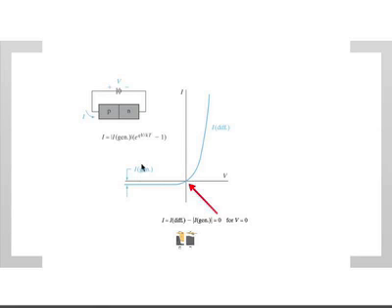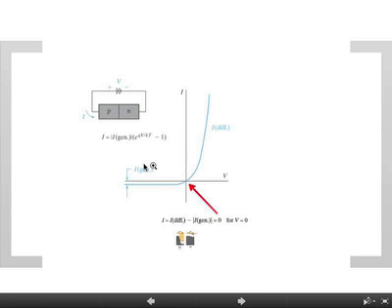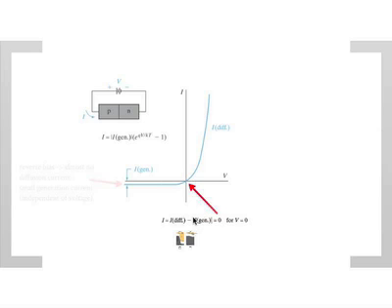And it's also called the generation current because this comes from the electron hole pairs that are thermally generated. Okay. So at V equals 0, of course, it's equilibrium. The two currents have to cancel. The diffusion current and the generation current have to cancel. The diffusion and the drift. That is 0.